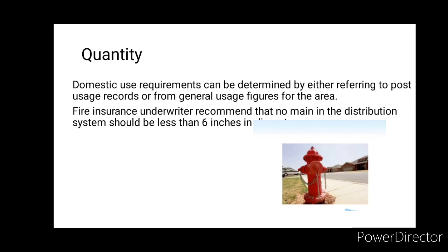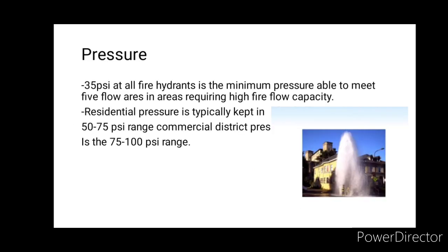Third is pressure. 35 psi at all fire hydrants is the minimum pressure able to meet fire flow needs. In areas requiring high fire flow capacity, residential pressure is typically kept in the 50 to 75 psi range. Commercial district pressure is in the 75 to 100 psi range.